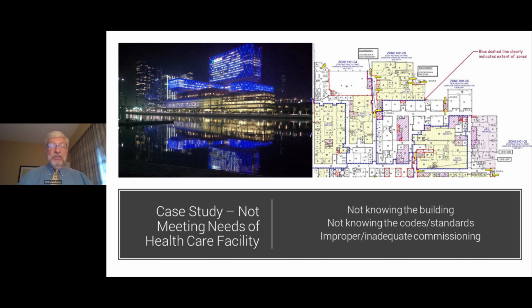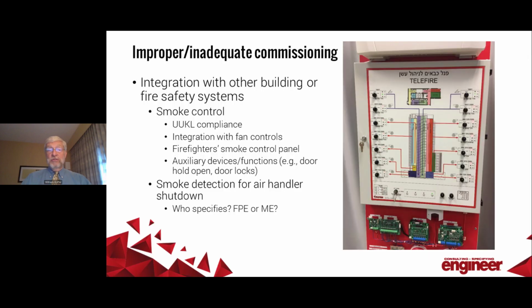We didn't design this. There was a lot of detection in this building. One of the things we found, not so much with detectors, because they're addressable and it's fairly easy to correct, but with other initiating devices like water flow alarms, was that they were not coordinated with the smoke compartments in that healthcare facility. So when they wanted to implement an emergency plan that called for certain things by smoke compartment, it was a rather expensive change after this system was installed to meet the owner's needs. So again, have that dialogue with the owner up front.